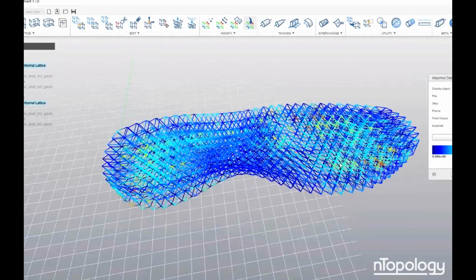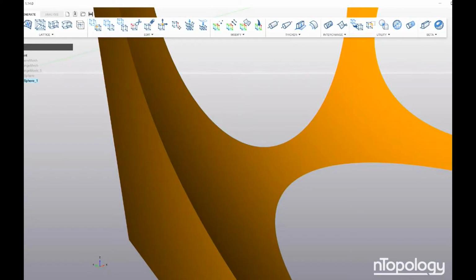The graph allows us to represent really complex lattices based on the medial axis. You can represent the middle surface, and then with attributes, you can apply thickness to get your final part. The narrowband level set is a volumetric representation, which allows us to do really clean booleans and unions while maintaining a really nice hard edge between parts.